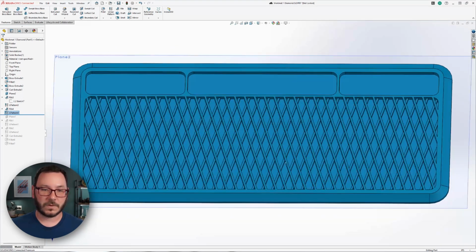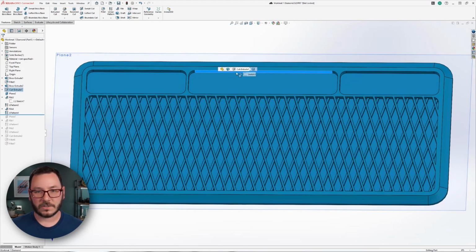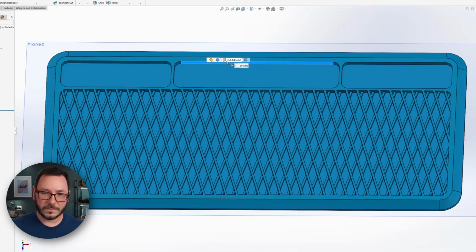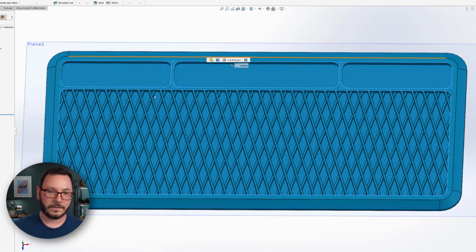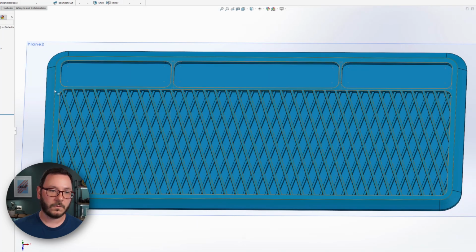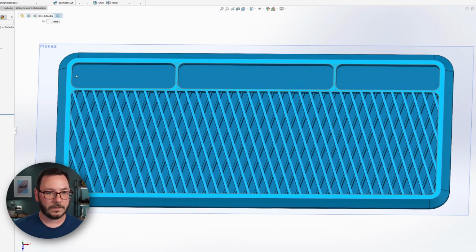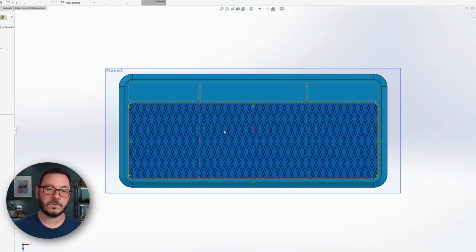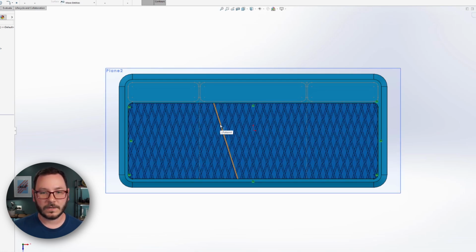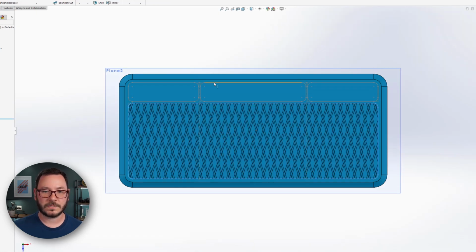I'm just going to use the sketch that we already created. So let's find that sketch. I'll use my breadcrumbs here, just selecting the D key again, and we'll find the original sketch that we used. I'll turn that on and we'll copy this off. We'll just create a sketch again on this top face. And I'll select this little region here, select chain. I'll use my shortcut toolbar and copy that over using convert entities. All right, from here we can use our D key to escape.